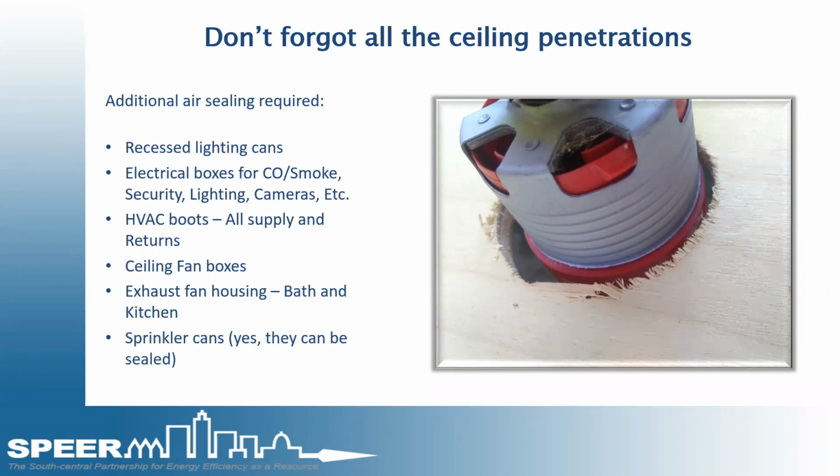Just like this, through a piece of wood, but it's resembling the same thing as what we see with sheetrock. It's cut very big. The cap itself goes over it, but is not airtight. There's no gaskets on the beauty cap that's on the bottom. So we've asked for those things to be sealed. Usually we have to go back to the fire marshal or the city, the chief building inspector, and say, how are we going to do this?